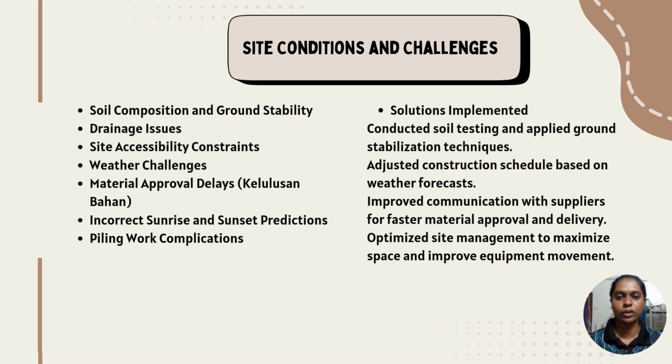After that, the site conditions and challenges. First, the soil composition and ground stability, which is varied soil condition with soft and uneven areas. This required thorough compaction to achieve a stable foundation. The uneven ground posed a risk to the stability of the construction layers.